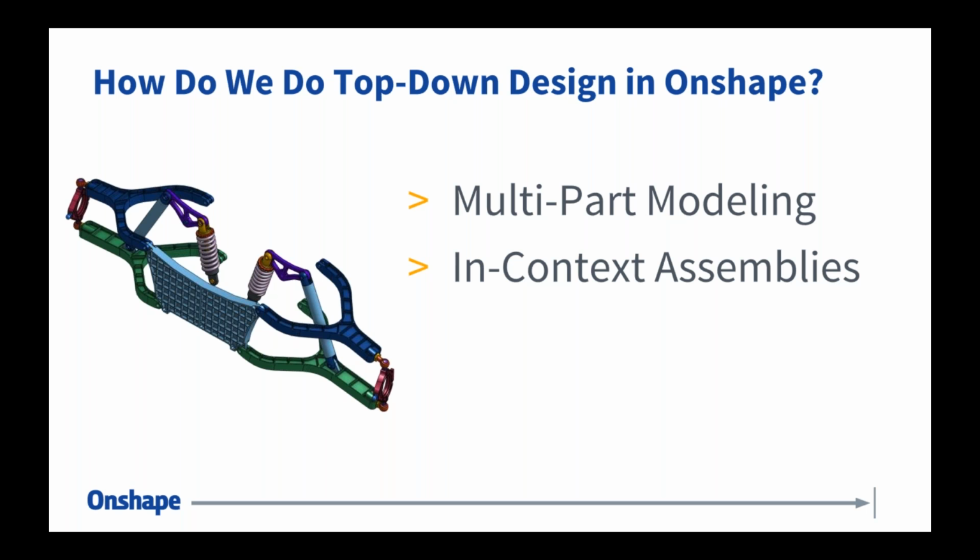Multi-part modeling is great if you're building all the parts together in a single space and you're starting from scratch, and you don't have to position a lot of things. But when we start talking about motion and having to position a lot of parts, then we start getting into in-context assemblies. I'm going to elaborate on this in just a bit.